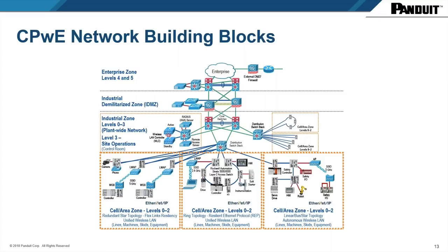On the factory system, the communication is real time. It's happening at nano and microsecond speed. When you go up to the enterprise, communication does not happen as fast and as frequently as it does on the factory side. So you separate those networks by a layer that we call the demilitarized zone. As you go up in the star architecture, you reach the central point, which we call the data center space, the enterprise space.